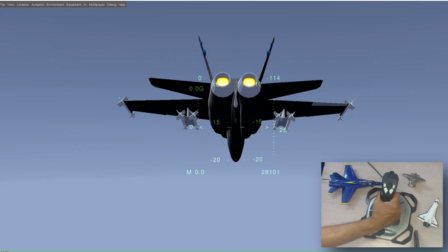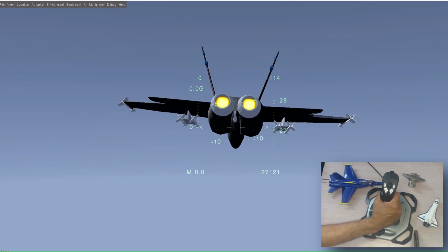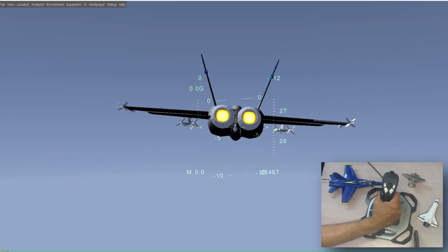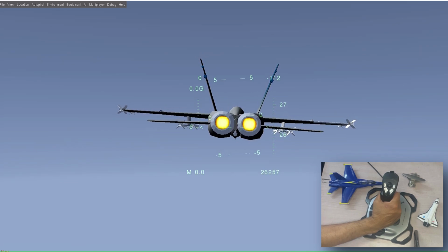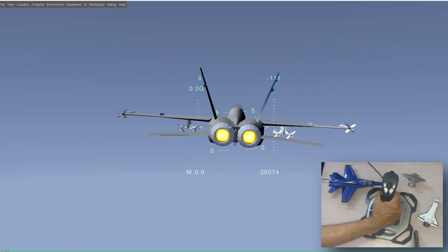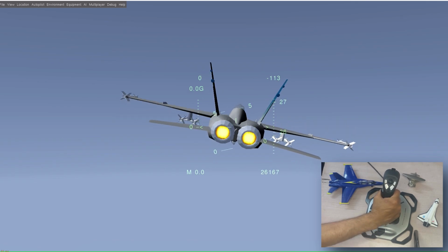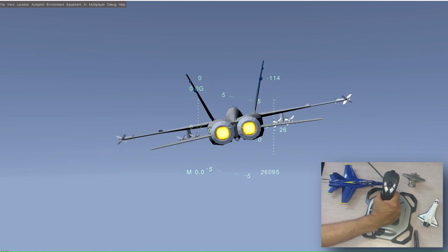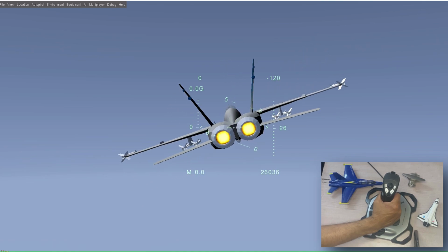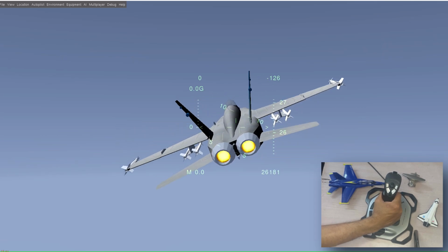So basically, what is happening? Whatever the computation is going on, you are sending the data: longitude, latitude, altitude, and position, phi, theta, psi, and then control surface deflection also. Okay, so real time simulation is running in MATLAB, and you are actually visualizing in FlightGear. That is the beauty of software like FlightGear and MATLAB. Using both, you can run the simulation and visualize the same.